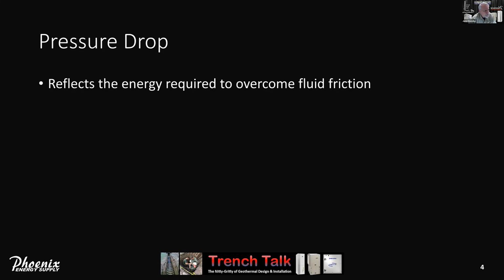We don't have to worry about vertical differences in our piping system or elevation changes. In a closed loop system, the water that falls on one side in a downward pipe is offset by the lift in the upward flow. So we're only worried about fluid friction.